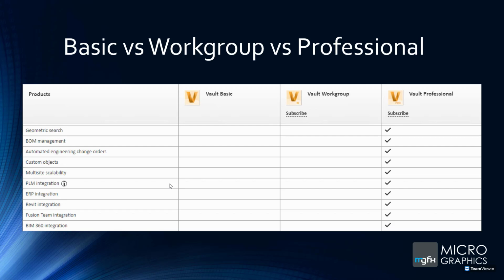So initially, when people do start working with Autodesk Vault, they just dump all the information in. There are a lot of duplicates because that's how they've worked traditionally with the Windows File Explorer. What Vault, I think 2020 Service Pack, or I think 2021, and only Vault Professional, did was a geometric search. So what you can do is you can say, what else looks like this? And it will go find all the parts and all the assemblies that it is situated in.